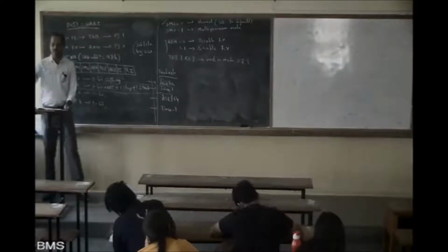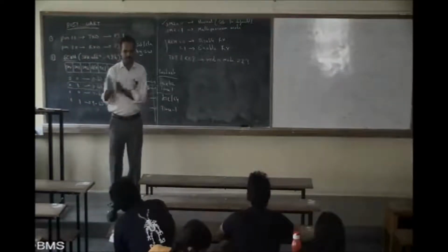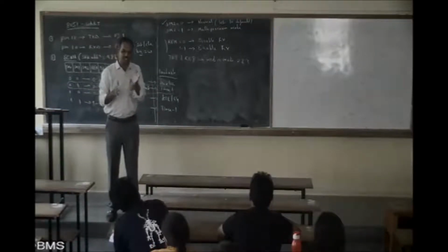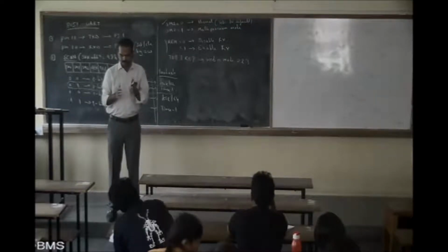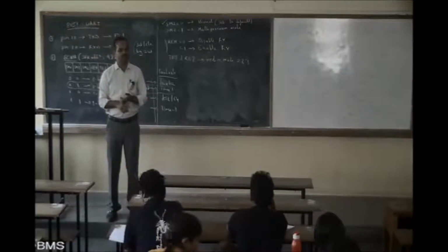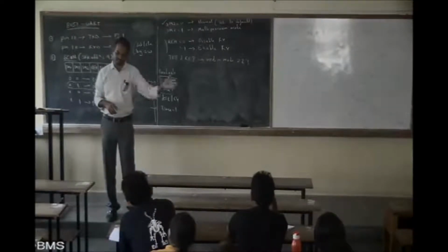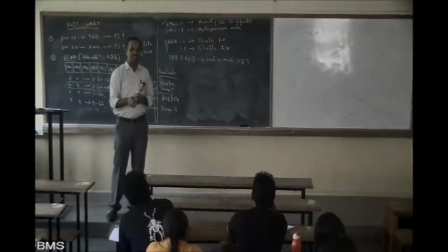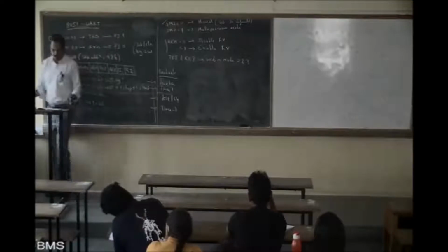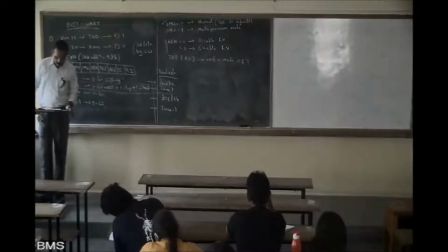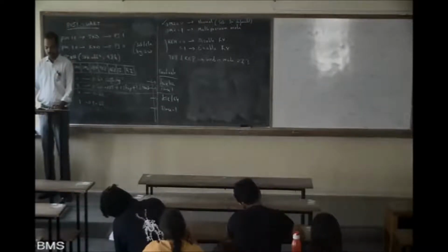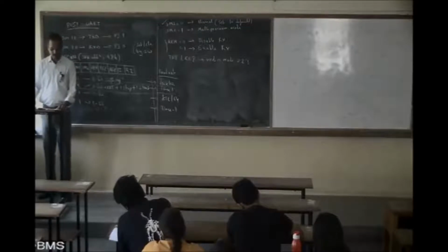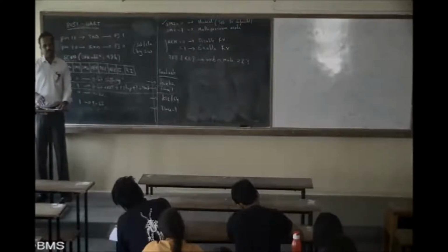You got it? What is the meaning? Whenever data is coming in, the start bit came, all 8 bits came, then the stop bit is coming. When it is halfway through the stop bit, it will set the RI flag. Or when the 8051 receives the complete data.